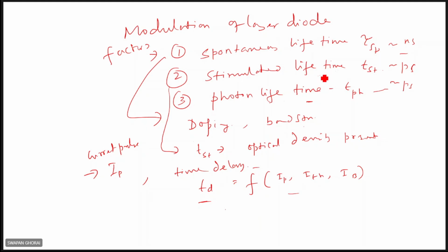The stimulated lifetime depends upon the intensity present within the cavity, and the spontaneous lifetime will be determined by the semiconductor band structure, doping, etc. Another lifetime is the photon lifetime, the lifetime during which the photons reside in the cavity before escaping.